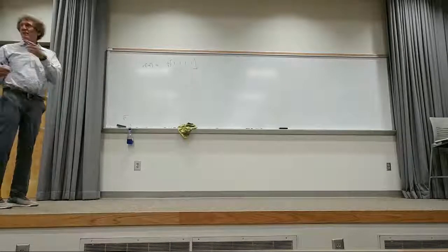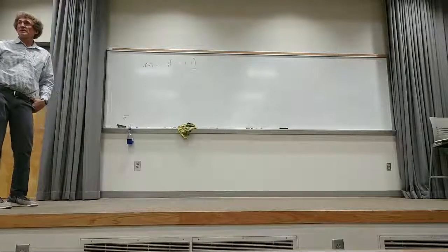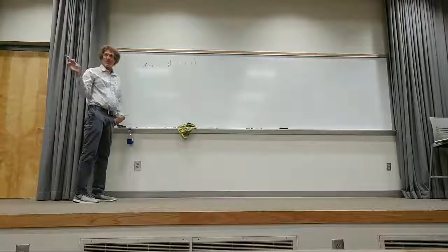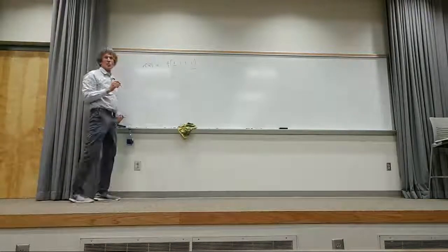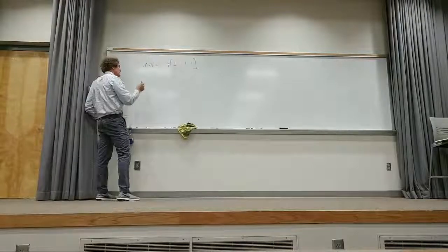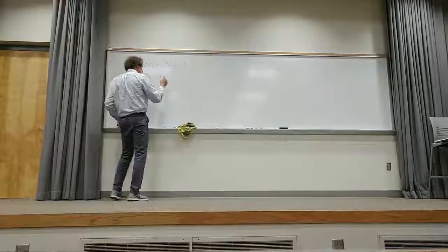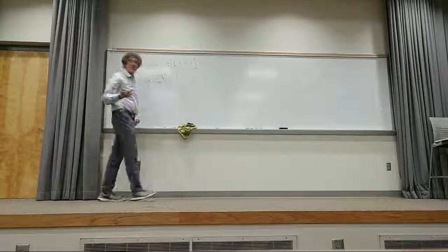Well, this is one thing I was going to show you. You can actually get the DTFT of a function and then simply sample the DTFT at the points associated with the DFT to get it. But I'm going to do this one just, you can brute force this. If you look at this, this is the first value, right? It's really a quarter, but that's the 0, where n equals 0. So you go through it, and x of 0 is really what? Isn't that just the summation of all those? It's the summation of 1/4, right? That's the value, and this is going to be for n equals 0 to 3, so that's going to be equal to 1. Isn't it, class? Just add them all up.